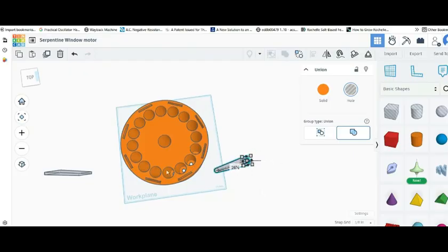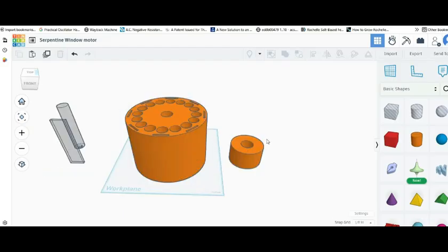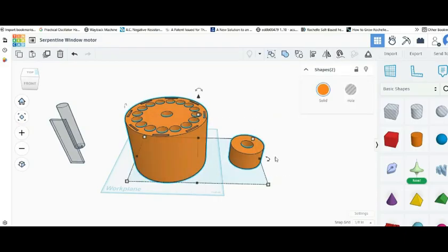The other reason I don't want to get too close in there is we need to extend this upwards in order to put on a place where we're going to put the other magnets for the pickup coils. So the trick is we're going to have to do it in 2 parts, because otherwise you have overhangs.